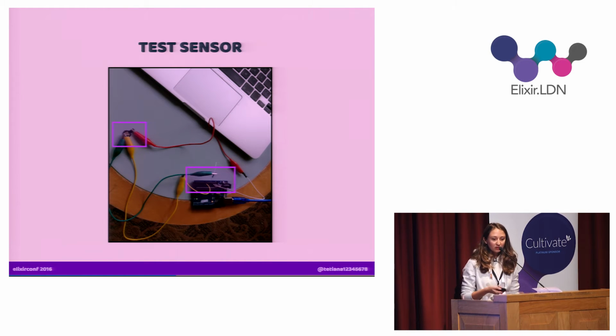There are some components which send digital signals, but with sensors, usually they'll be sending analog ones. So pick one of the analog ports on Arduino, and the other end of the sensor should go to the power. And the connection which goes to the analog port should also go to the ground. If you forget the ground, it doesn't work.